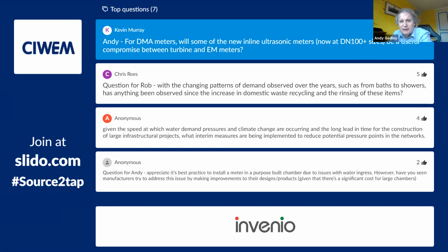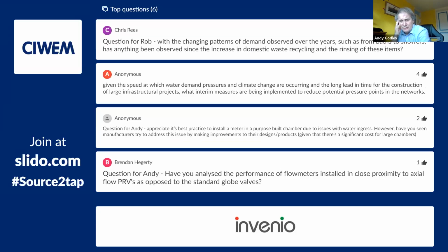There are a couple of concerns around sampling intervals with battery-powered meters, and around potential robustness, where they use reflectors within the flow to get an axial transmission of the ultrasound along the flow, so you've got something intruding into the flow. Now they don't all work like that, so perhaps there's a bit of finessing around that answer. But yes, I think the answer is essentially it's something worth looking at. We're about to start testing one in the near future, so it'll be interesting to see how well they work.